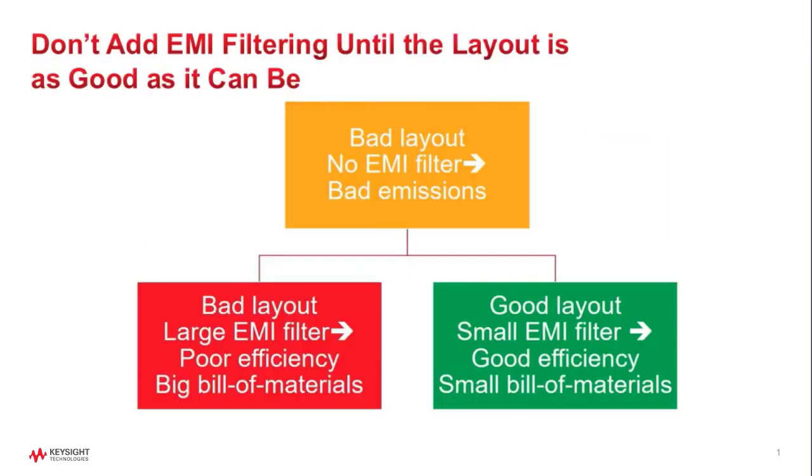All right, so this particular slide is from my colleague Colin Warwick, who was on the phone with us today to help answer any questions. And his issue here to point out was, in this case, you have a bad layout, no filtering, you have emissions that are not meeting spec. Don't just throw an EMI filter on it without some attention to detail, because it may or may not solve the problem.